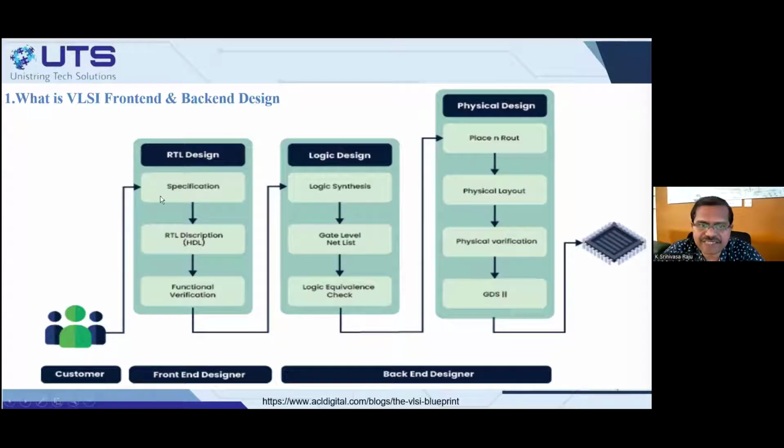So at the high level, you have a specification, you translate the specification to an RTL diagram, then use an HDL, hardware description languages like VHDL and Verilog, which describe the hardware. So you code using the RTL standard or RTL style, then you do functional verification. For this you use a simulation tool, could be ModelSim, could be the Xilinx inbuilt simulation tool, could be the Synopsys simulator. This is functional verification. In functional verification, we do not think about whether this piece of code is becoming a mux, whether this piece of code is becoming a register, or what the clock speed is. That is not addressed here.